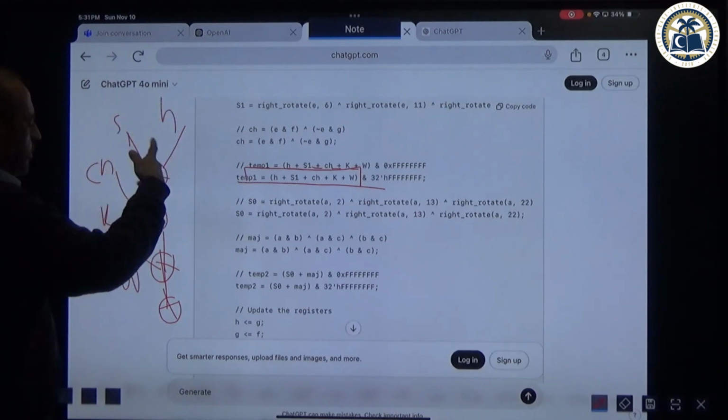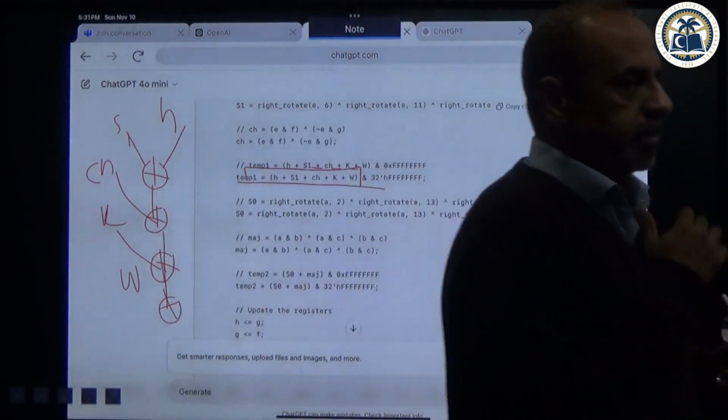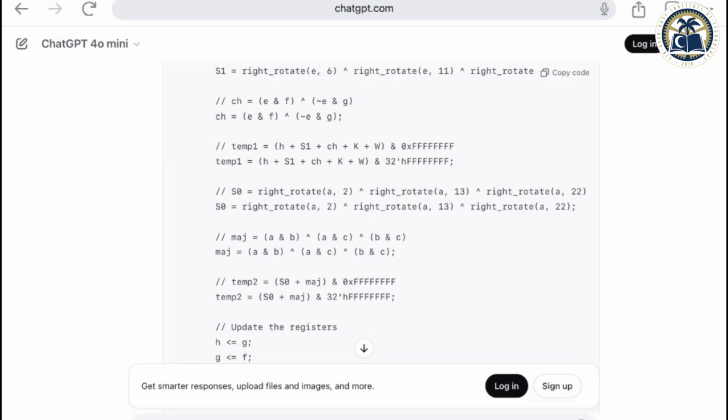So I can find some interesting way to add this, but this is my combinational cloud, doing all of this addition. This would determine how fast I can clock my SHA-256 algorithm, because it's also feedback, since this iteration will be fed into the registers again. Once you have a feedback algorithm, it is even more challenging to add pipelining. We cannot just add a register, because that will delay the computation.